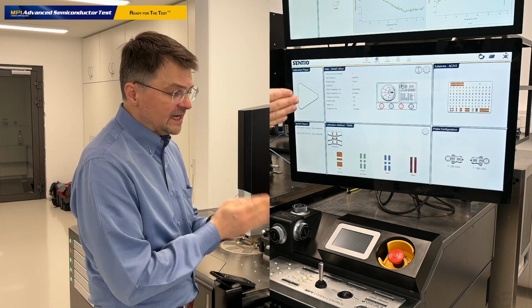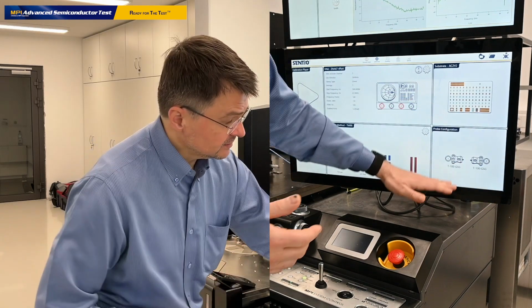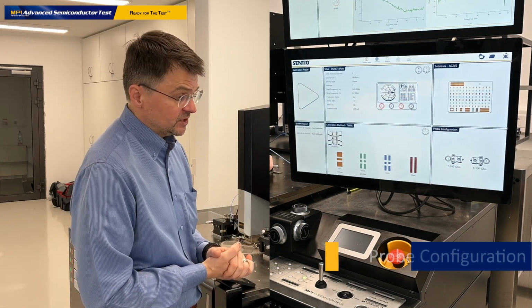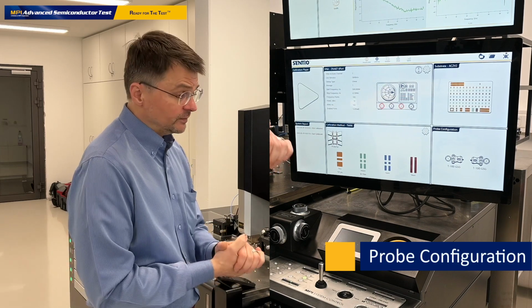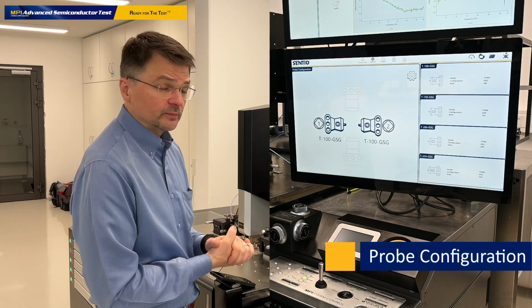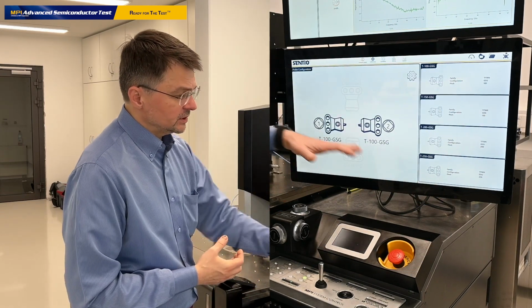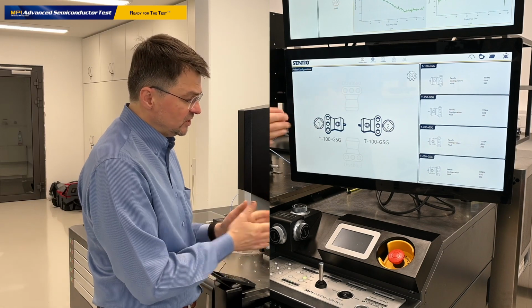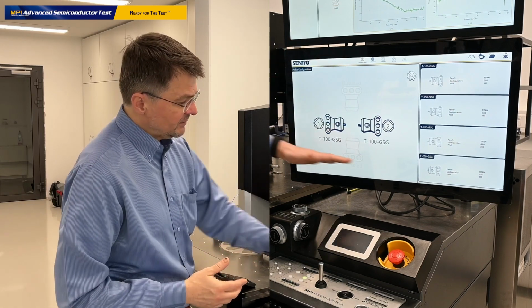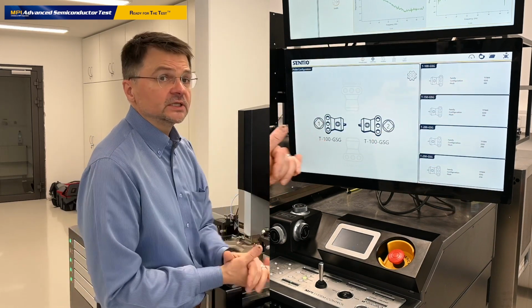We have Titan 125 micron pitch probes, and the system is currently configured for Titan 100 micron pitch probes. So I need to change the type of the probe. Just click on the widget of the probes, and you're immediately led to another settings window, another widget, which helps us to reconfigure the probes, where you have the current configuration zoomed in, and a list of recently used probes.